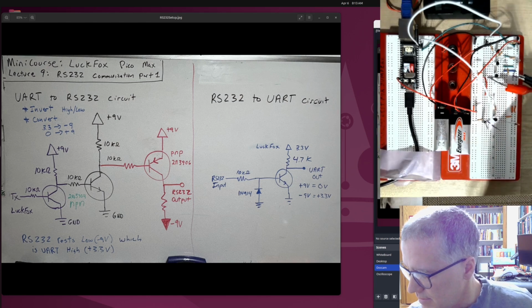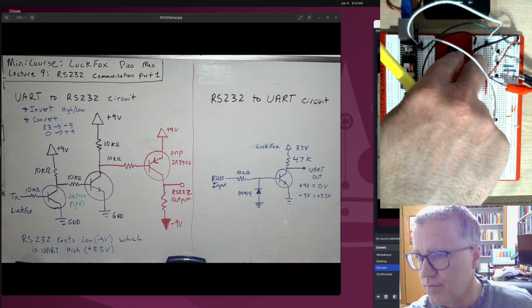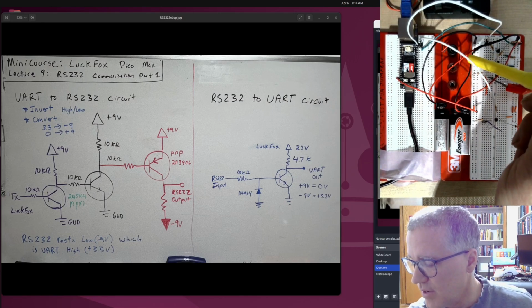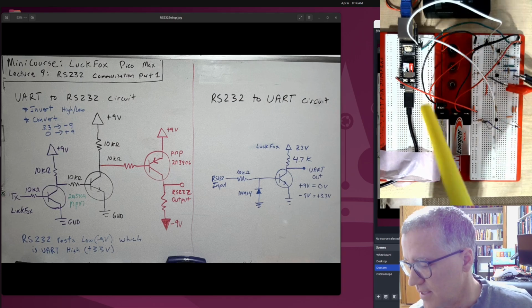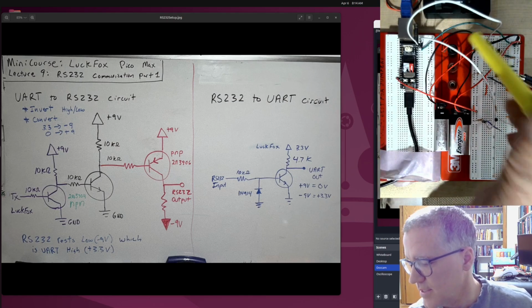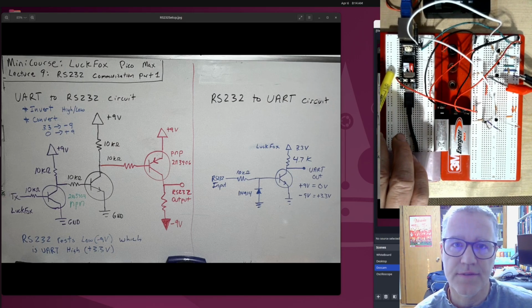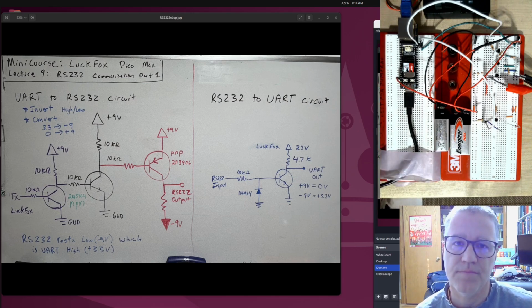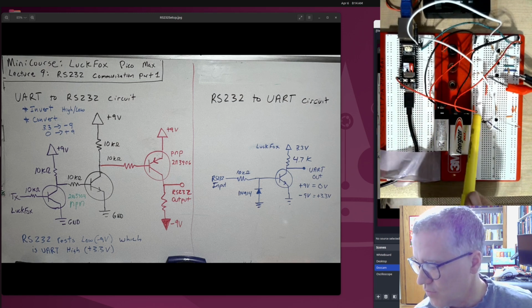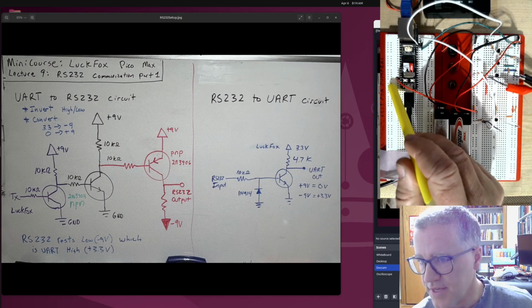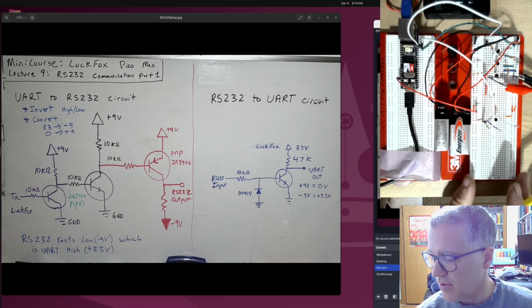So we can see this positive wire, that's the plus 9 volts. This is that combined wire from the negative wire from the one battery and the positive wire from the other. So that is coming here, and then finally this black wire here is the minus 9 volts. This red wire is coming from the system pin, the 3.3 volt pin from the LuckFox, so the 5th pin down on this side, or 5th pin up on this side, I guess, as you're looking at it, and then over to this rail. So that's powering this breadboard.